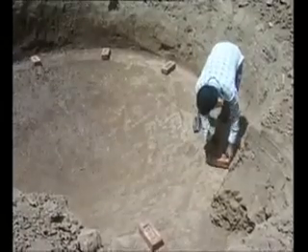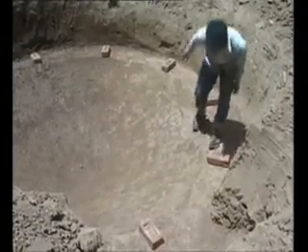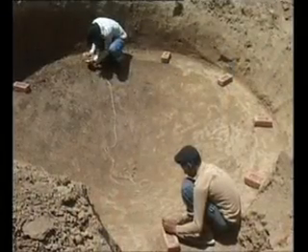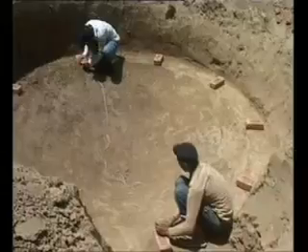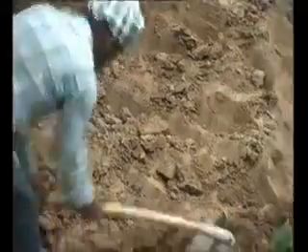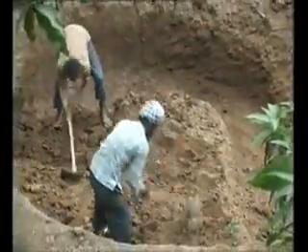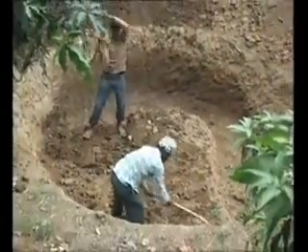The digester pit is dug 3.5 feet deep. Now we mark a circle as per the actual diameter of the digester of the proposed biogas plant. After marking the diameter, we further dig a semi-spherical pit which acts as a foundation of the digester.